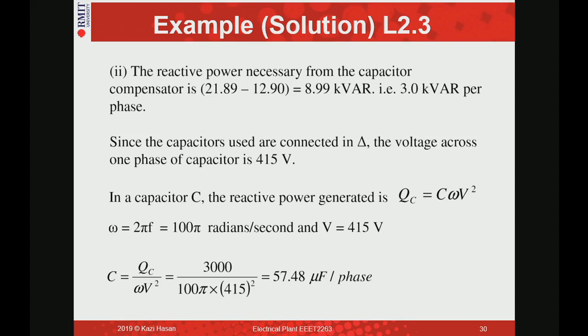So the power factor correction is very similar for single phase and three phase. We just have to consider that for three phase, the reactive power needed is 3 times more, so we calculated per phase at the beginning by dividing by 3.